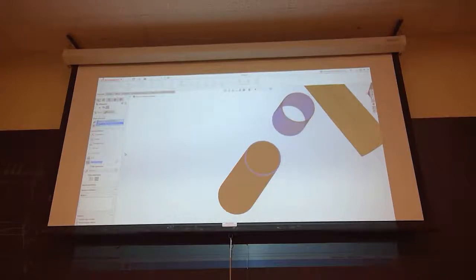Did you select, and then select tangent to get inside? No, you want to select the face. Not the edge, please. You want to get the face. Make sure you zoom in over here; wherever you put your mouse is where it zooms. Then the face of the other one. Once you get there, make sure you hit 6 inches, right? Because that's half of 12. All right.